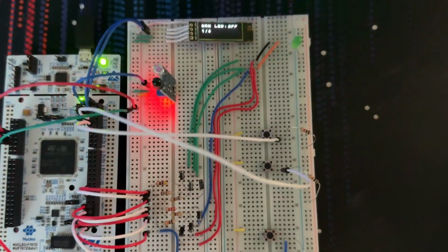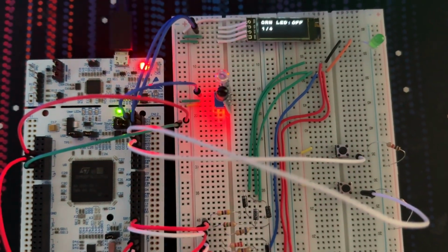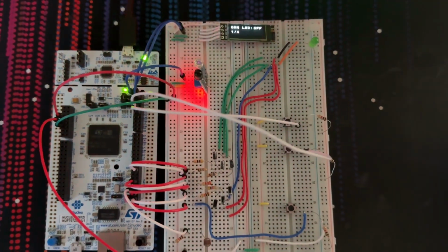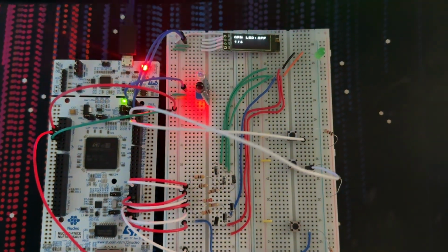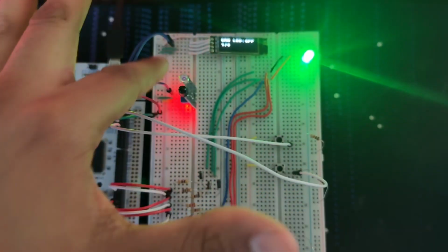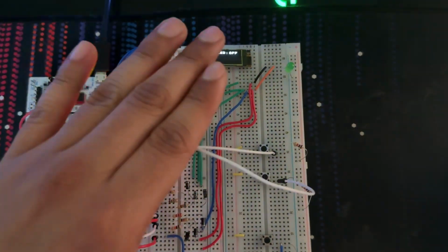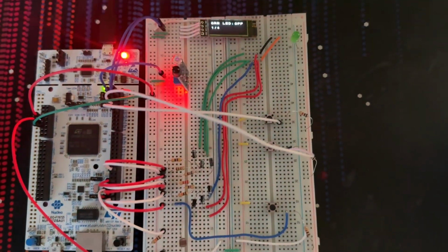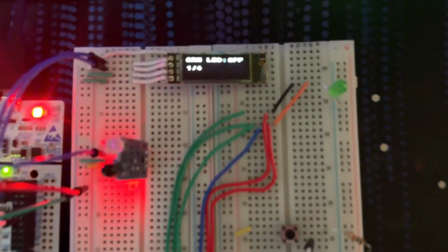So this is the motion sensor that Ryan is going to be talking about now. Yes, the motion sensor is basically a modified IR sensor where if you put your finger or hand above it, it'll receive different amounts of light, which will trigger it to turn on the LED and communicate with the OLED. And we can see that happening right there.